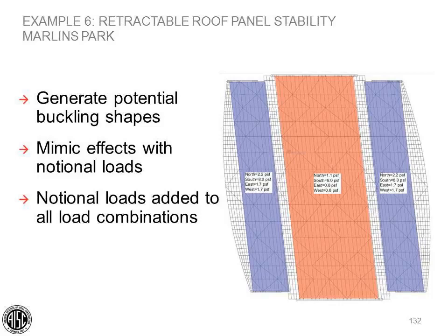First of all, if you just take a simple column and apply the 0.002, that represents the forces that build up in the system from a h/500 displacement. And it certainly is optional to apply starting displacements instead of notional loads, and that's allowed by the specification and appropriate as well.